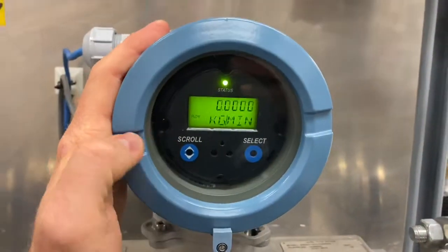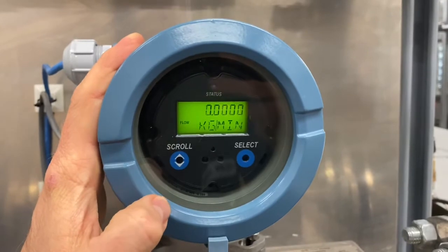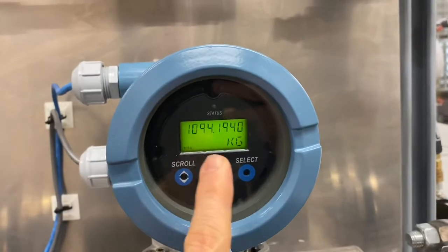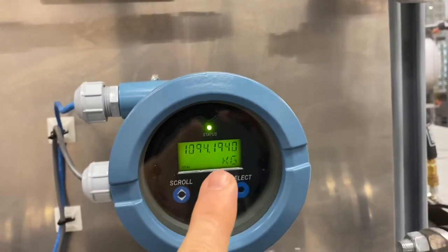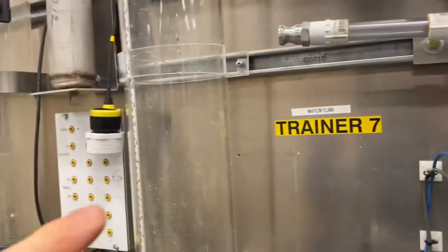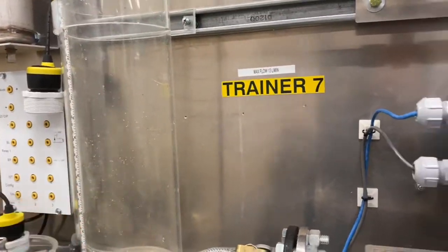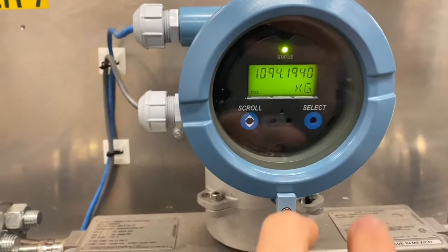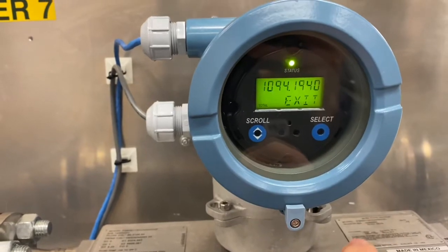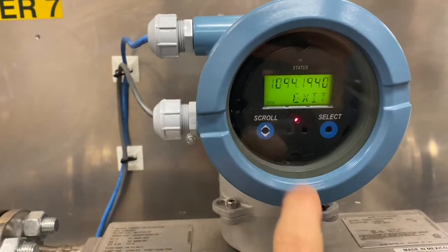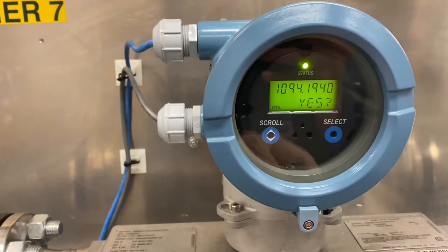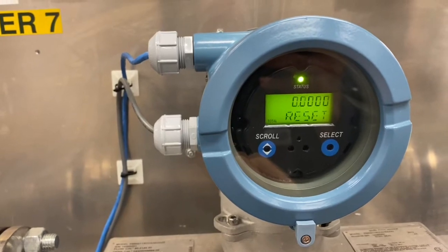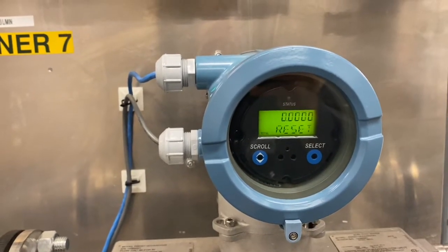So I've exited back out to the main menu here, and we can scroll, we can see our mass flow right there. What we want to make sure is that our meter is displaying the total kilogram value here, because we're going to be comparing the total kilograms that have flowed through this meter to the kilograms of water that are in our tank here. And so we can set this value to 0, clear it. If we hit select, scroll over, and then press select reset, and it's going to say, do you want to reset? We say select for yes, and there it's back, it's down to 0. So it's ready for doing our first run.